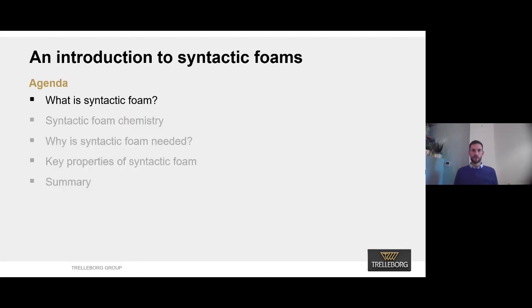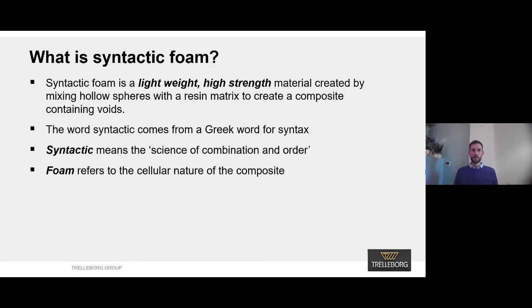So firstly, what is syntactic foam? Syntactic foam is a lightweight, high-strength material created by mixing hollow spheres with a resin matrix, and this creates a composite containing voids. The word syntactic is actually Greek and comes from the word syntax, and it means in scientific terms the combination of order, and this refers to the combination of hollow spheres within the resin matrix. The word foam refers to the cellular nature of the composite itself.